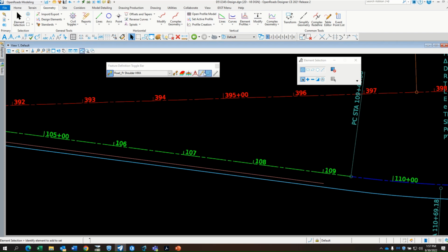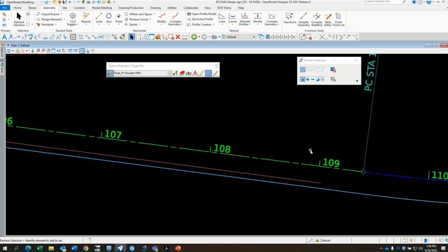Especially when you're going back to when you use that feature definition and you have persist snaps turned on, and you snap to something, and then you're telling it, my intention is to connect this line, and then I go make a change to some other line. It's going to continue to be connected depending on which snap you used, perpendicular or something else.